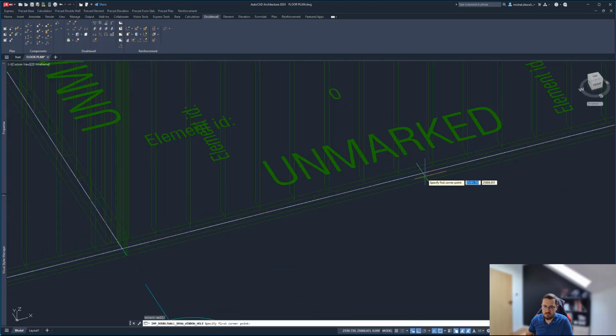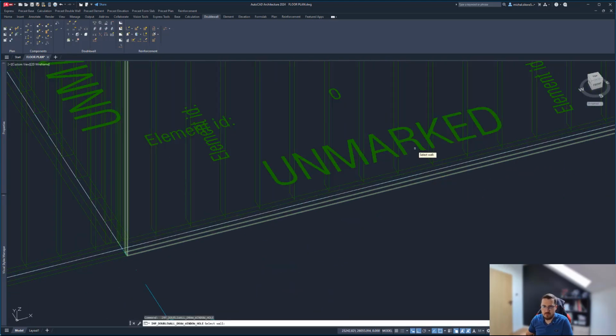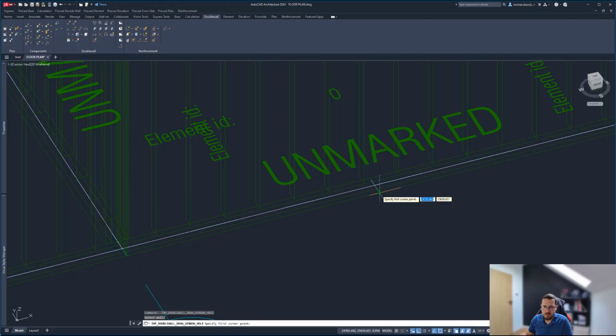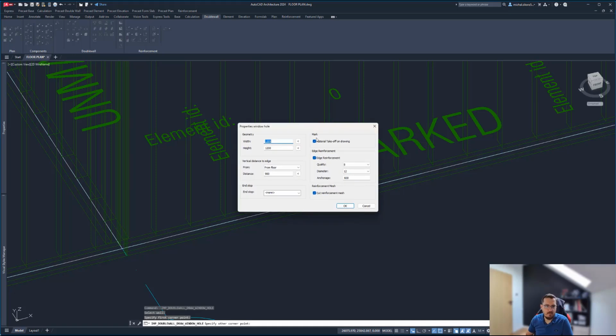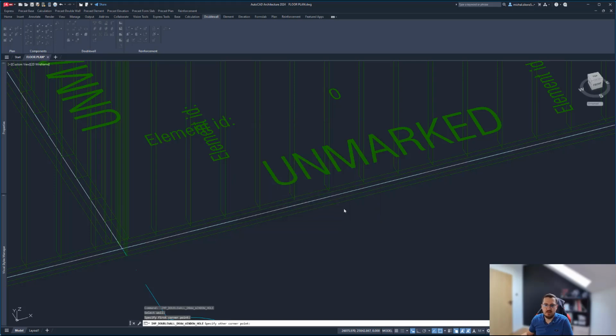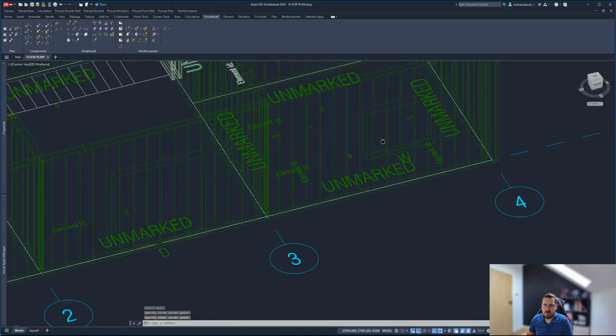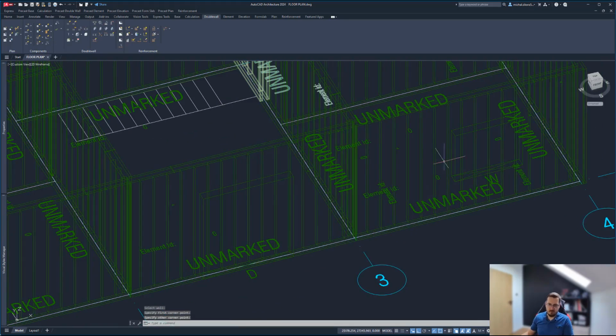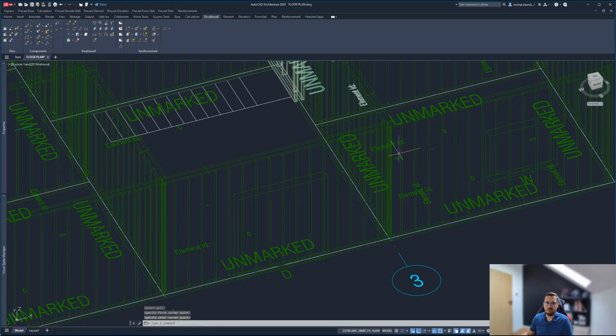Select this wall. Oops, I didn't select the wall. Okay, first corner here, like that. Let's go 150 distance from floor and 900, which will be perfect. Let's maybe add another end stop as well. Okay, and this is our opening. That should easily cut the meshes later when we do that.